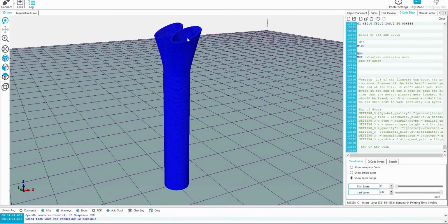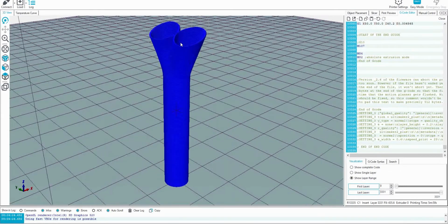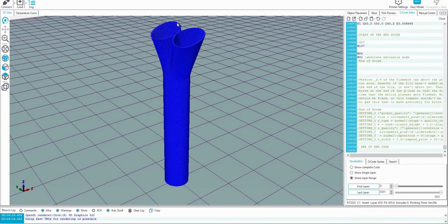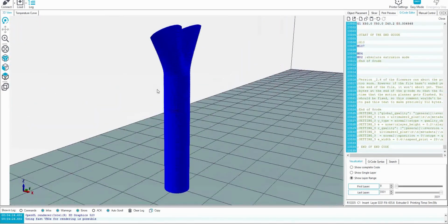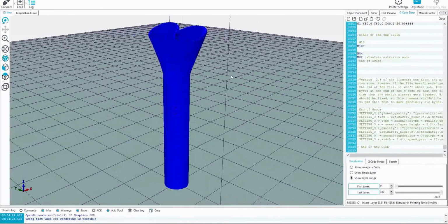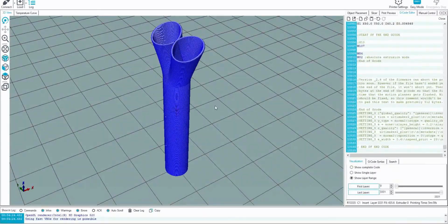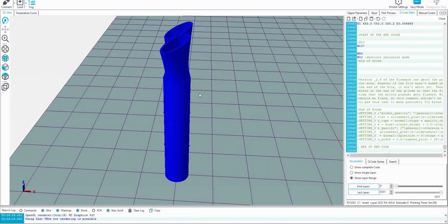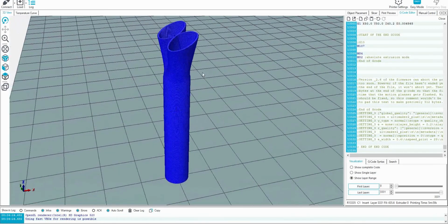If this top section wasn't printed in a non-planar format, then towards the top it would only be printing these top arcs and then have stringing in between and defects. So the CAD model would be much worse quality and actually very difficult to produce, and the STL file would be for some structures extremely large, whereas in FullControl you might describe all those details in less than a kilobyte of text data.